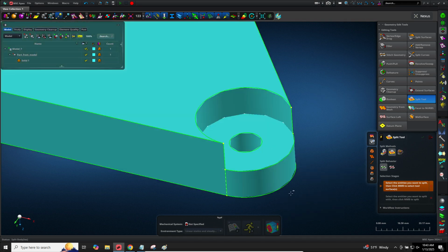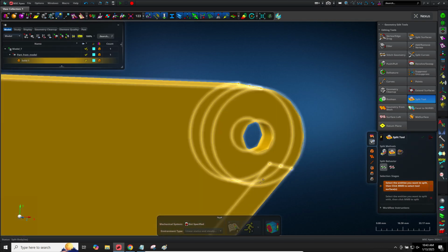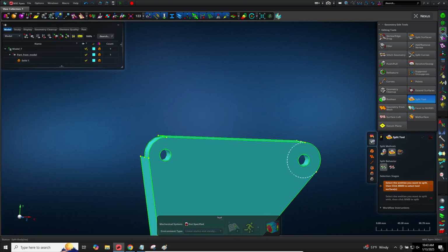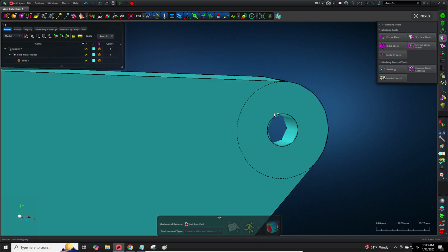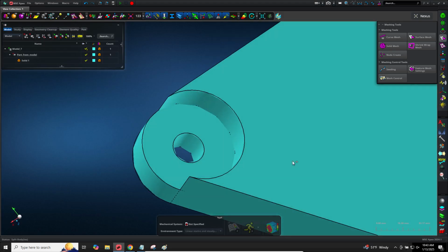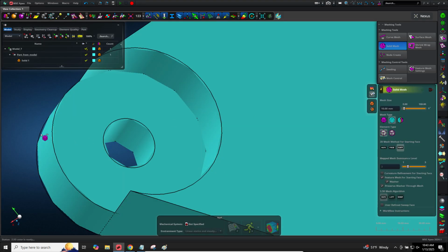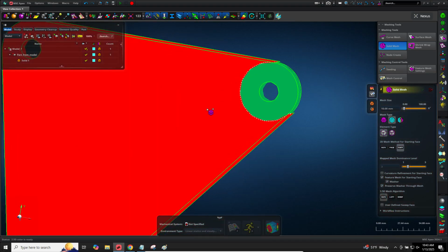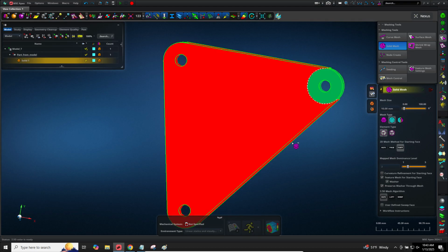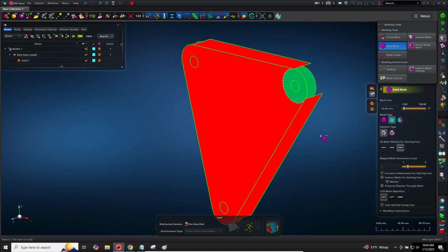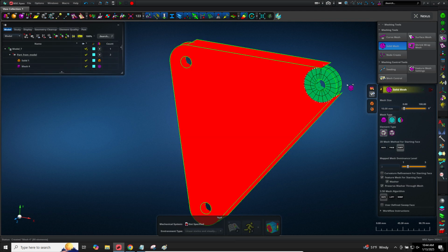And now I have a partition here. And I know it's a partition because there are actually dotted white lines here. If I go back to the hex mesher, you'll notice that this face here is similar to the opposing face. So if I go to the hex mesher, this partition or this cell can be hex meshed, again, because one side is similar to the other side. So if I wanted to, I can select that geometry and I get a hex mesh here.